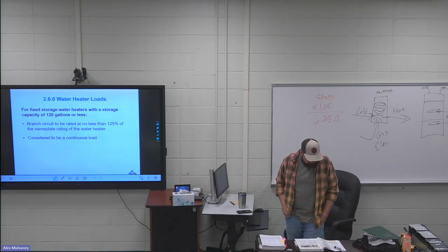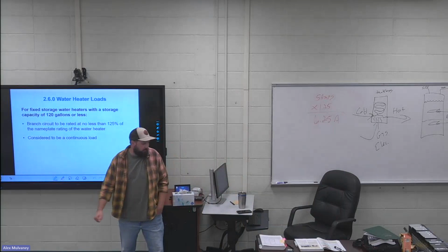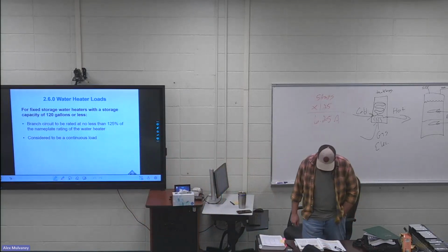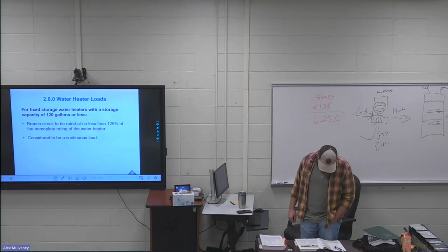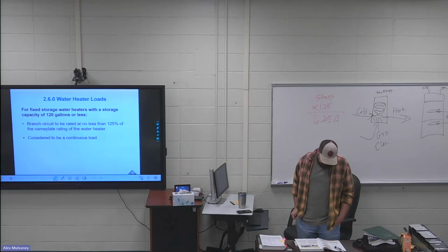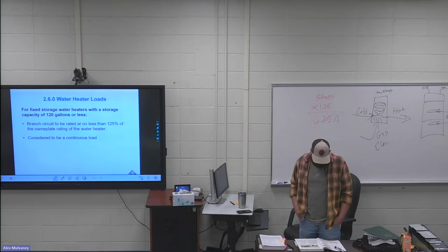Page 15, electric heating loads. These are what you guys, unless you move up north, will never see. Page 15, right above example 1, the second to last sentence is highlighted. When space heating equipment utilizes electric resistance heating elements, protection for resistance heating elements shall not exceed 60 amps per NEC section 424.22(B).